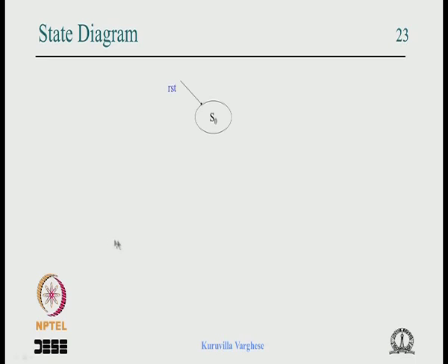So see, at power on, you come to a starting state, S0. At that state we make the signals inactive. This is the starting state: signals are inactive, SOC is 0, FIFO write is 1, counter reset is 1. That is the output of that state. Here we are waiting for the start signal. If start signal is low, remain there. If start signal is 1, go to the next state, and we make SOC 1, rest all remains the same.